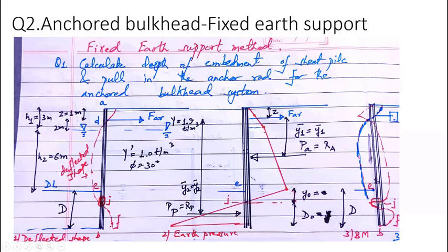So this J becomes the point of contraflexure. This blue which I have shown, if the sheet pile wall depth is small, then the bending moment diagram for anchored bulkhead sheet pile wall with a shallow depth goes like that. So the point of inflection is less in that case.